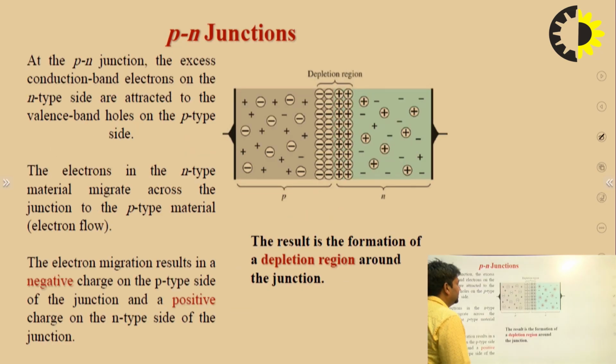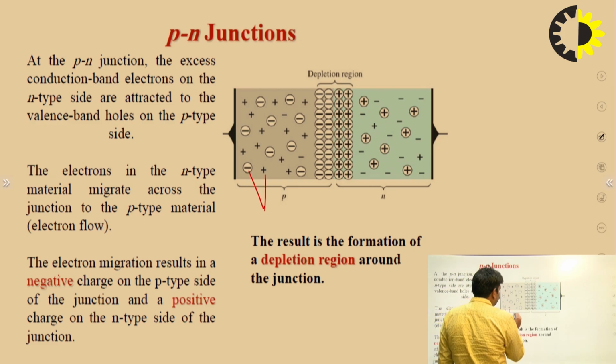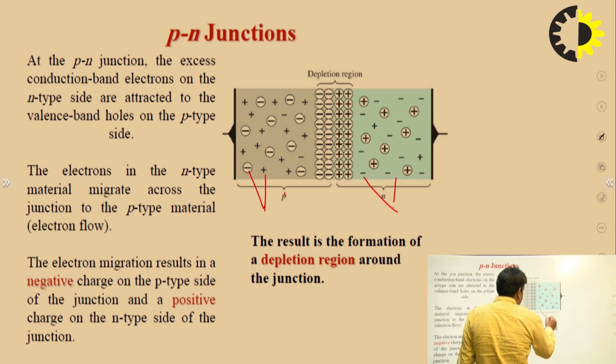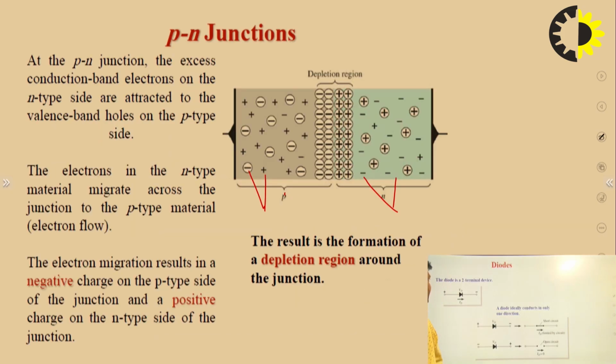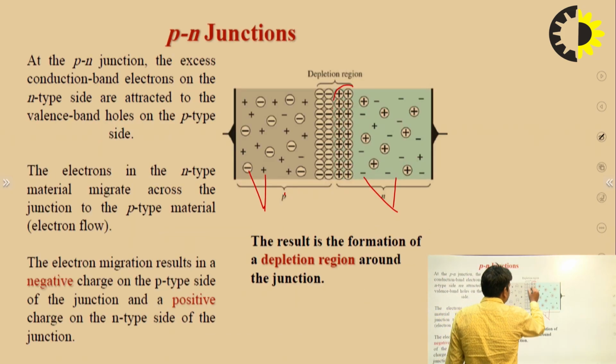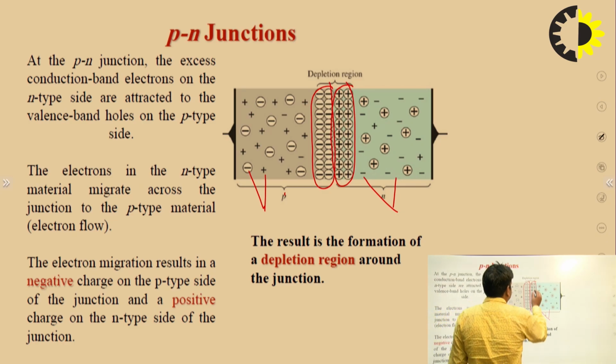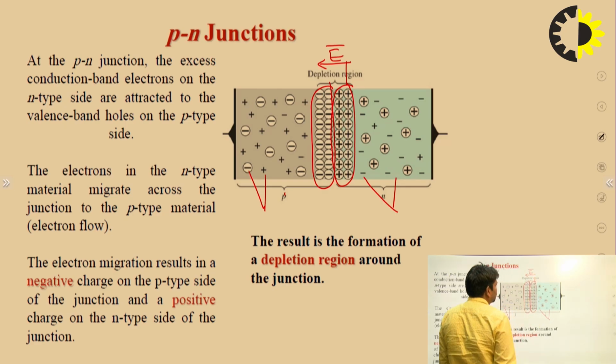In the p-n junction diode, on the p side the holes are the majority carriers, and on the n side the electrons are the majority carriers. And these are ions, the immobile ions. On the n side, these are the donor ions, and on the p side, the acceptor ions. They also produce an electric field from plus to minus, which we can call a potential barrier.